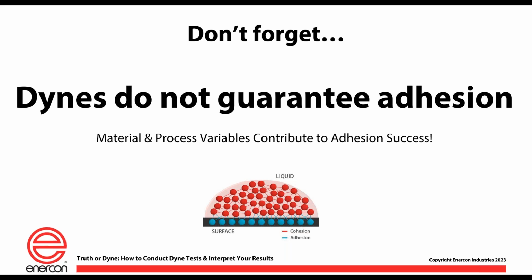And usually it's as a result of a misunderstanding in doing the Dyne test. So basically the Dyne number that they're comparing it to, they think it's one thing, but in fact it's something else. And truthfully, the industry has not helped us in this regard because for many of you out there, you may not realize this, but we have moved as an industry less and less of these tried and true solvent-based Dyne solutions to these glycol-based or environmentally friendly based Dyne solutions that we use today. And to further complicate that, people don't even realize what solution they get. They're not even looking at that. So they didn't even know that, number one.